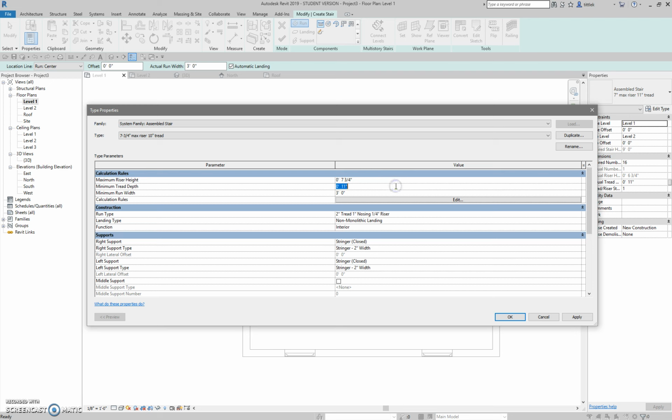And in this box, notice I'm not clicking and using my arrow buttons. If I click on a box over here past the actual dimension, it highlights the whole thing and I can just type 10 inches. I don't have to monkey around with left and right and all that kind of stuff.